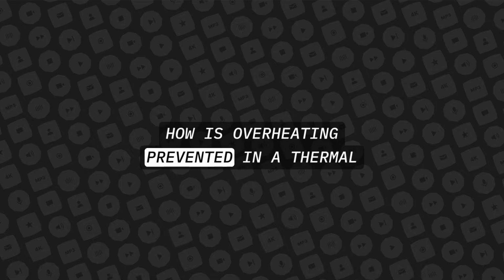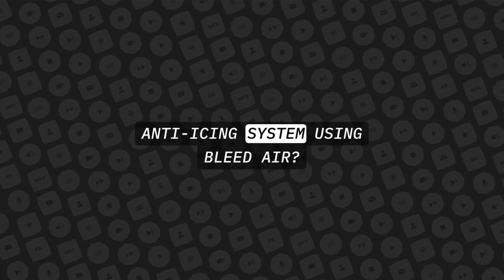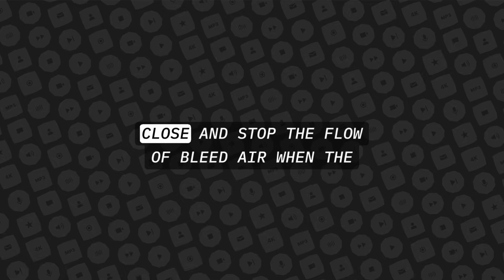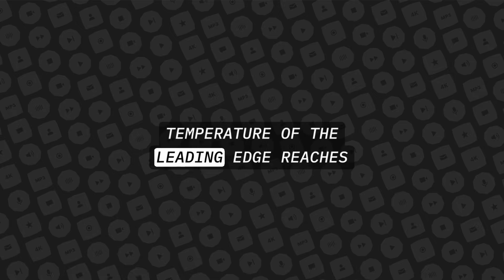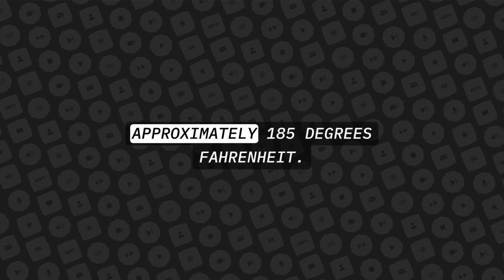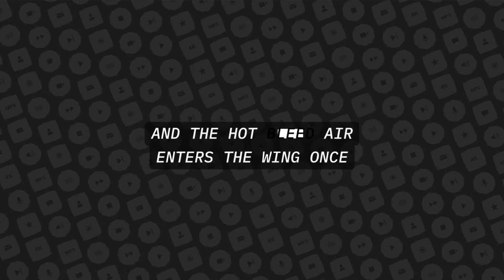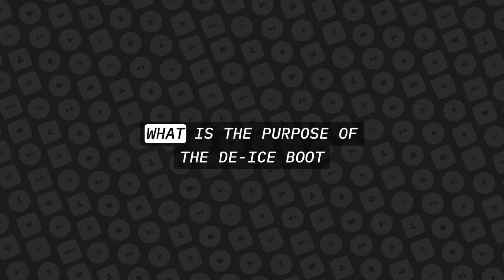How is overheating prevented in a thermal anti-icing system using bleed air? A thermal switch will cause a shutoff valve to close and stop the flow of bleed air when the temperature of the leading edge reaches approximately 185 degrees Fahrenheit. When the temperature drops, the valve opens and the hot bleed air enters the wing once again.